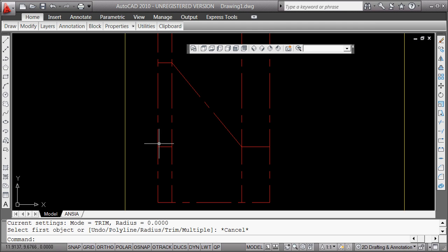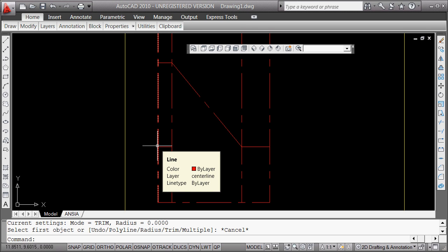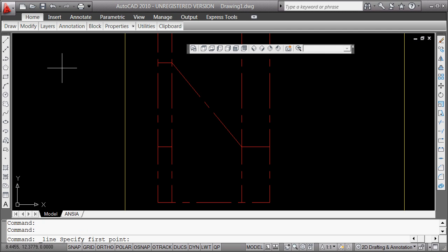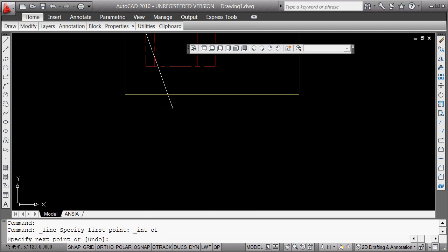F for fillet. Well, we're not going to fillet that yet, but we could fillet these 2 pieces here if we wanted. But now you see you are given actually an angle. It is telling you that this angle here is 60 degrees down, which is a -60. You'd have to think a little bit about that on the other side, but mostly you're also using visual clues here. So I'm going to go ahead and draft a line. Shift right click from the intersection. And at this point you learn to draft really long lines and then cut them off. So I've got a line there.